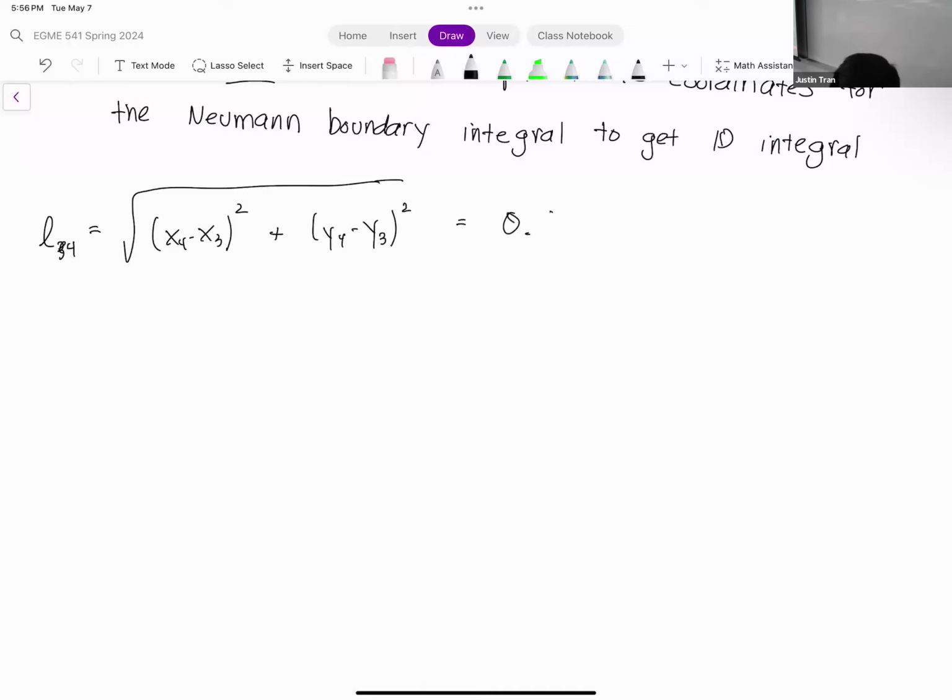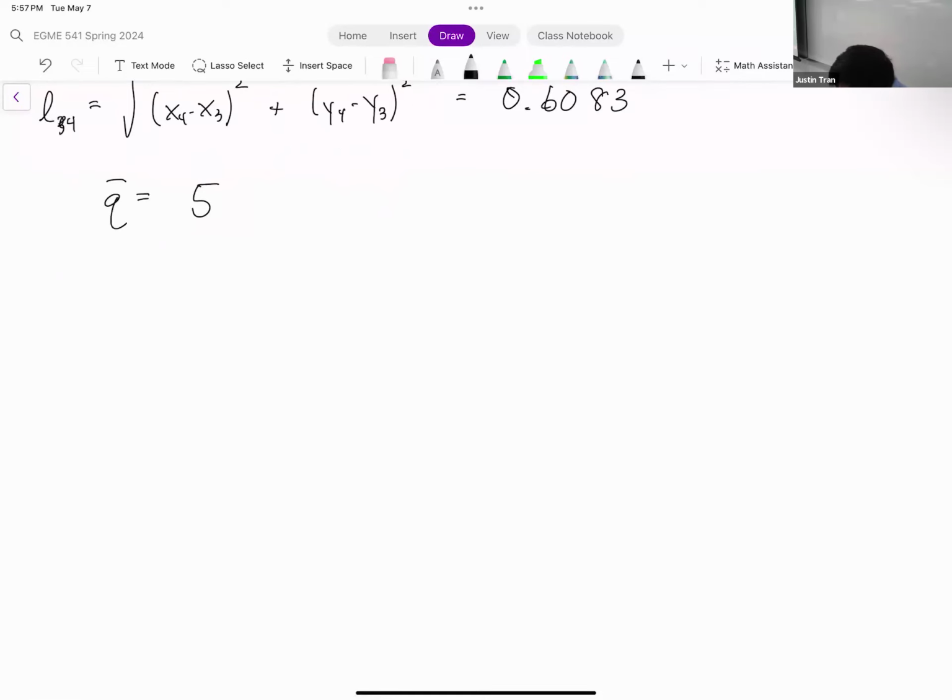And so the integral that we're computing here is an integral from -1 to 1 of the shape functions of xi. Eta is equal to 1 in this case because it's at a fixed value, times Q bar LE divided by 2 d xi. We have a minus sign as well, just because of how it comes from the original weak formula.